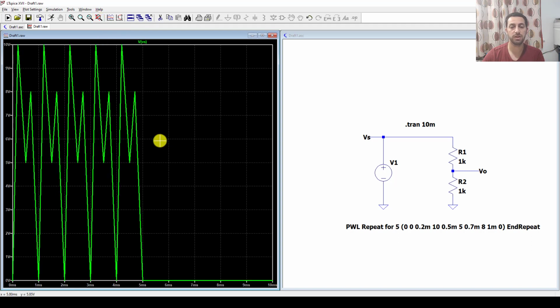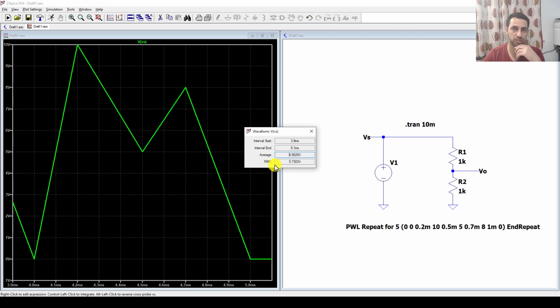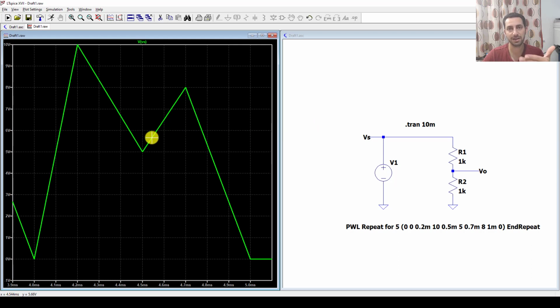Let's now return the signal, and now I will show one cycle. If you show one cycle or different cycles, it is the same. I will show one cycle and consider it as a repeated cycle, and now we go to the signal name and get the value, which is 4.9 volts as average. We don't care about whether it's correct or not, but I'm showing examples of how LTSpice considers the calculation of these signals.